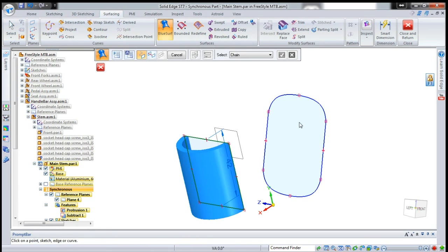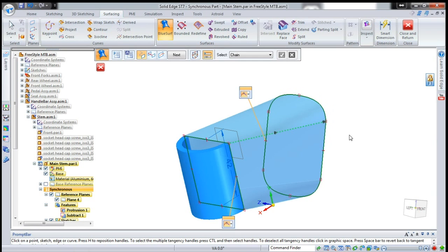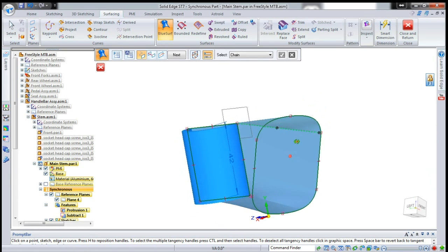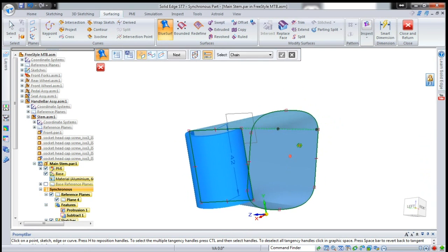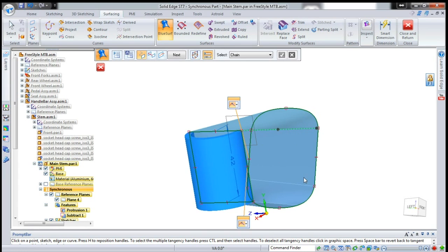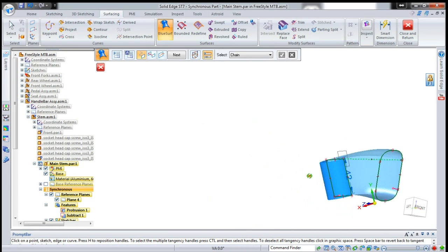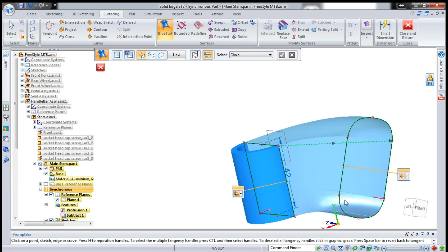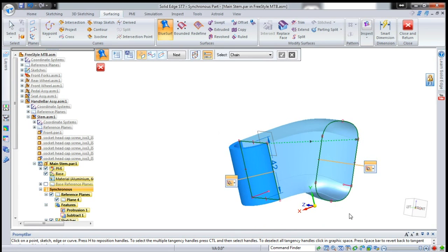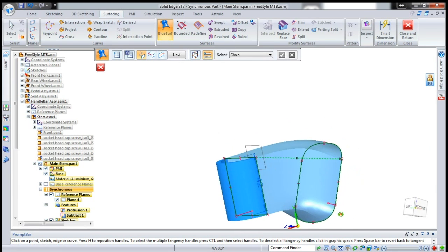Now, I have various options for doing this, and a blue surf is a very rapid option, and you'll notice it's given me a reasonable surface at the moment. However, I might want a little bit more curvature control. So I'm going to make these areas normal to the surface, and just by dragging my handles I can control the shape a little bit more.